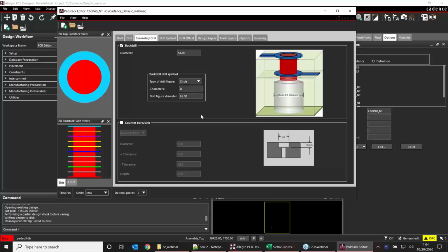So the constraints on dielectric thicknesses are, number 1, materials available. Number 2, the impedance, the modeling and the kind of trace widths you want. If you are able to have a 3 mil trace for 50 ohms, you can as well do a 2 mil dielectric height. Of course, if you don't want to use traces less than 5 mils, then your dielectric height can be 3 mils upwards. So there are 3-4 factors in deciding the dielectric thicknesses.